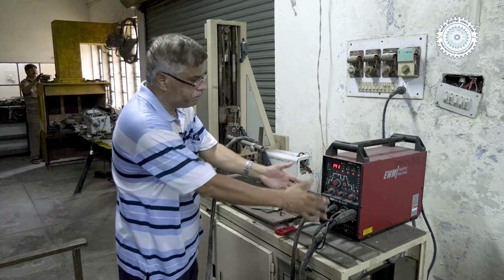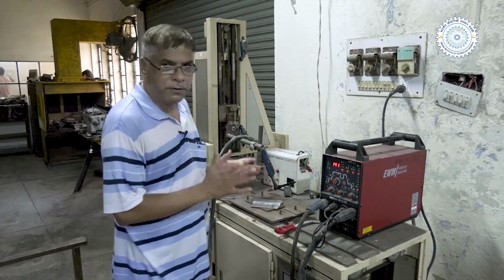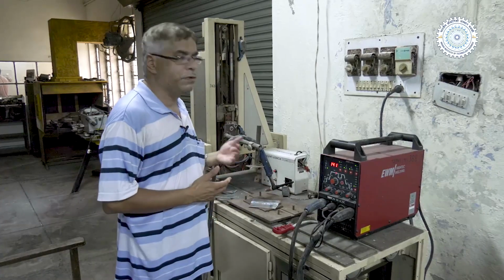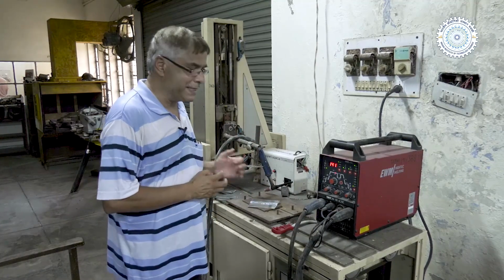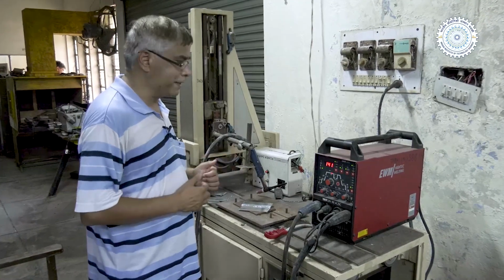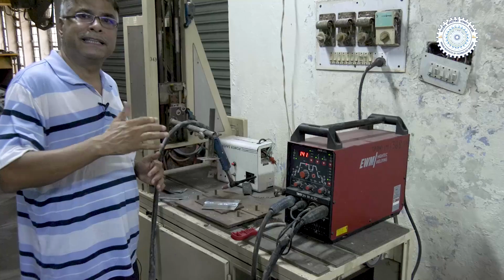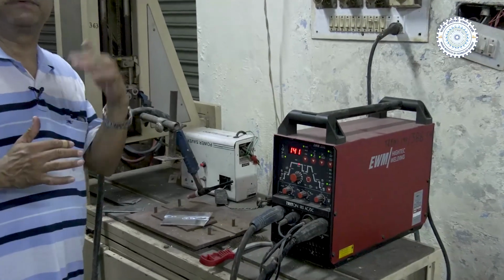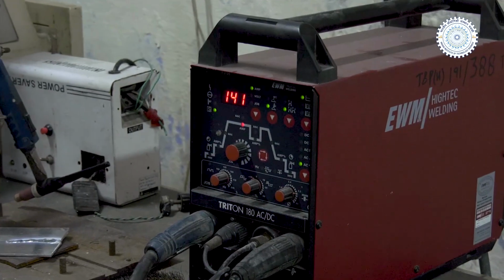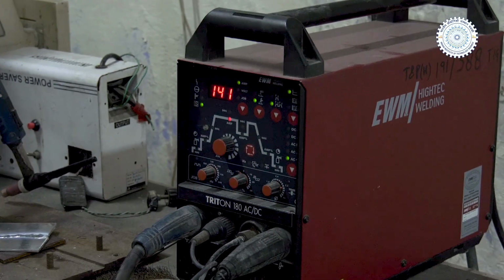So, here we use the welding power supply, which is comparatively of low capacity range. It has both options: DC, which is used for development of high quality steel weld joints, and AC setting, used for welding of non-ferrous metals. And here you can see there is an option for pulsing the welding current, where we can set the background current and the peak current, and the welding can also be done using constant current as per the need of the heat to be generated for joining sheets of a given thickness.